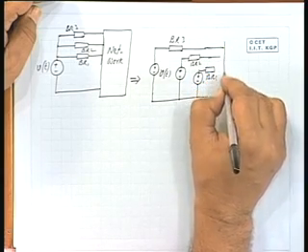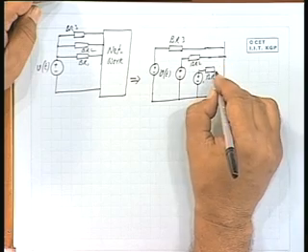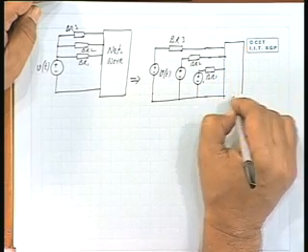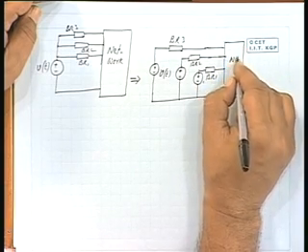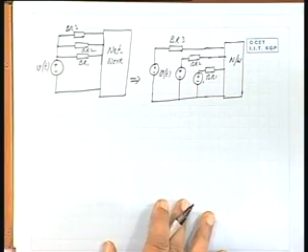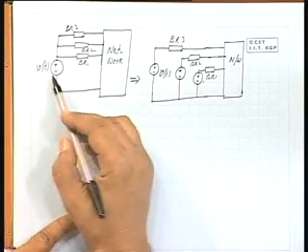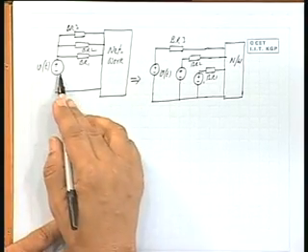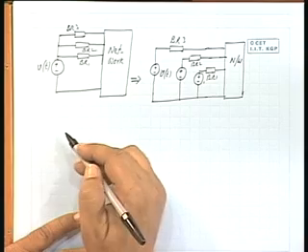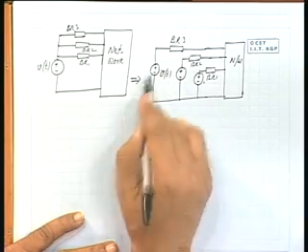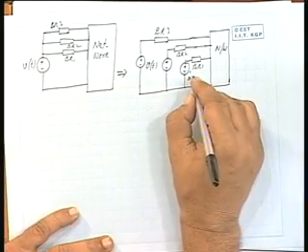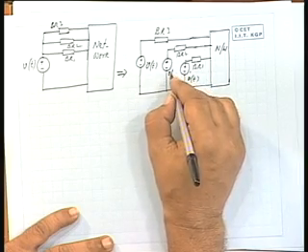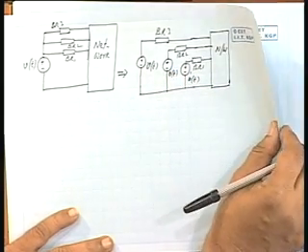All these are connected to the same network segment. So, what we have done is replacing a single voltage source by multiple sources of the same magnitude Vt. This is also Vt, this is also Vt. At times it simplifies our computation. Let us see one simple example.